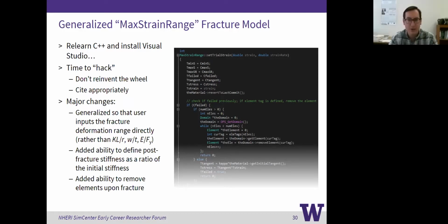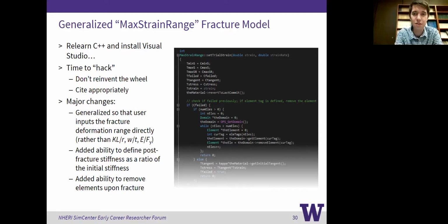So around the convergence issues, how did you solve the problems you encountered? Any suggested solutions or strategies? Yeah. So my suggestions would be, it all comes down to your analysis algorithm. I know there's a bunch of different algorithms that people use, where you're reducing the time step or changing the algorithm itself that's used in OpenSees.